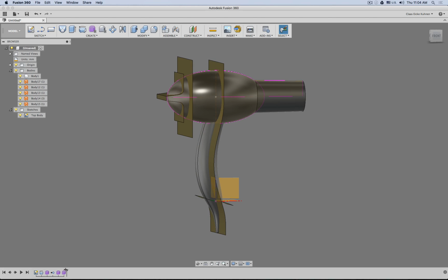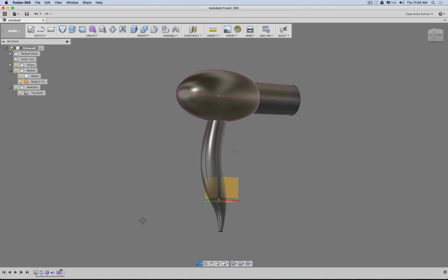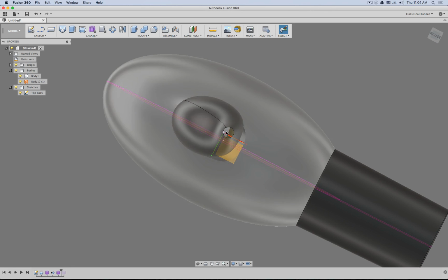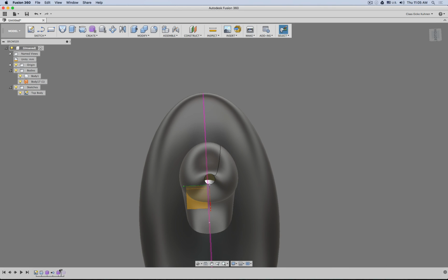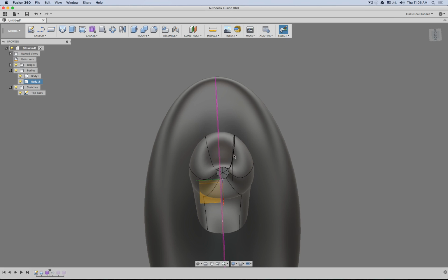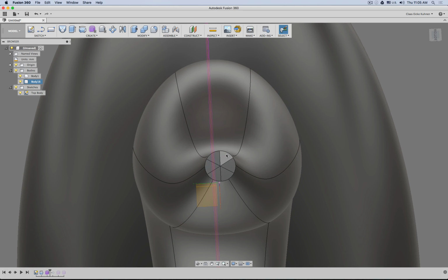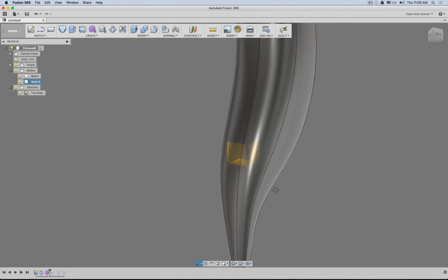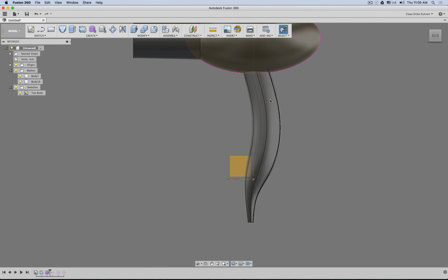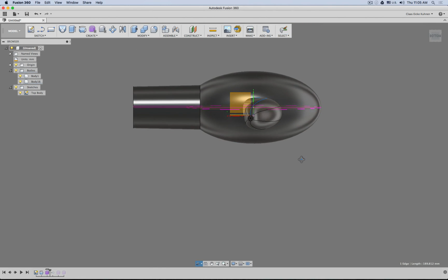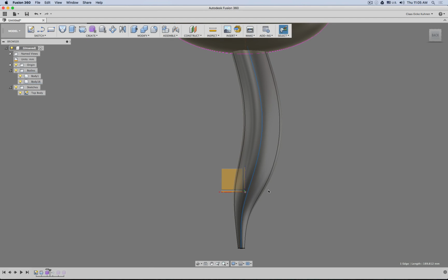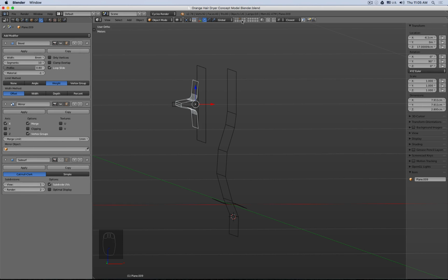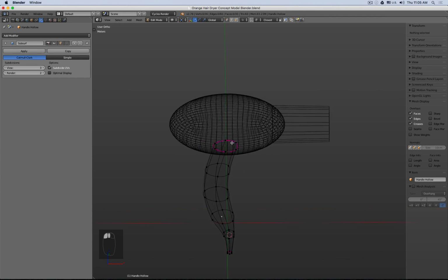Before I continue, I want to go back one step. Here's one handle. Pay attention to that this is open and it's a nice and smooth geometry. And here this one is closed, but I have all these lines. And then there's this cap stuff with all these lines. I'm a little bit nervous about it because we want to split this one along the side, and then these lines might actually perfectly line up from the side with my split surface. So what I did was I